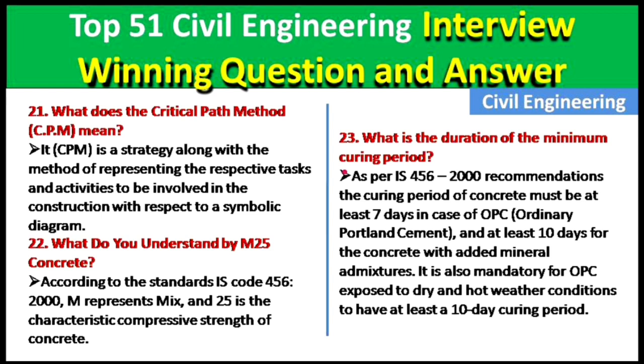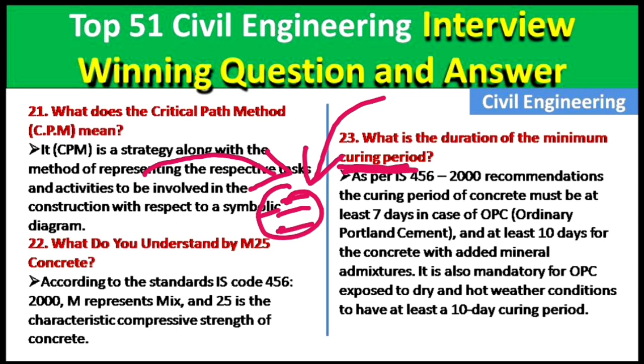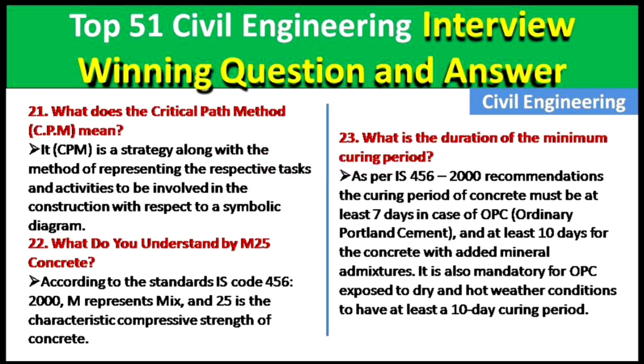Okay, so curing time, what is meant by curing time? First of all, curing time is when we prepare a concrete, then we have to provide water to it to get its strength. So this is known as curing. Okay guys, so how long should we provide curing on the concrete for different structures?